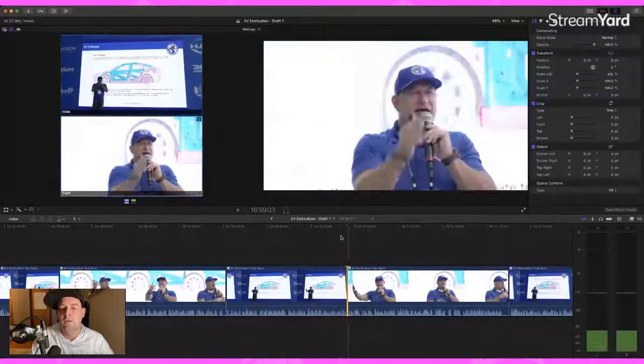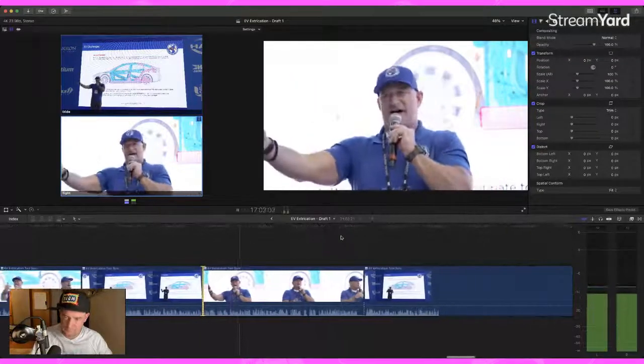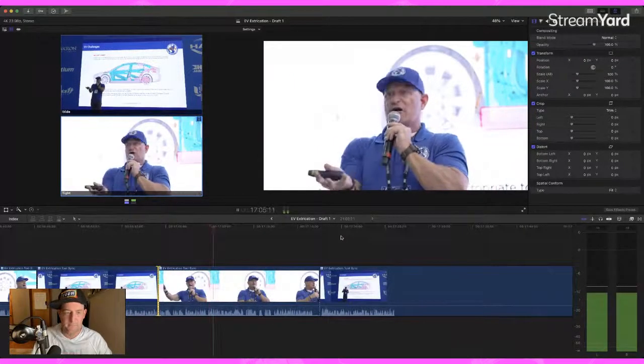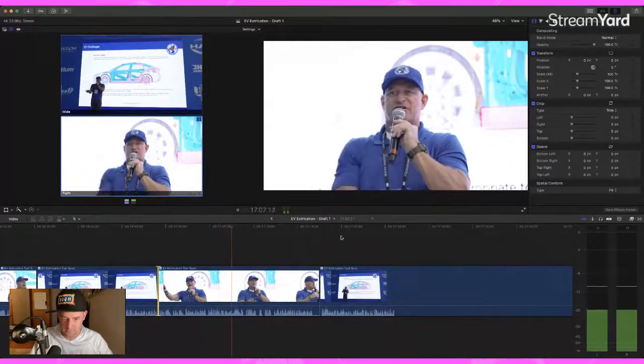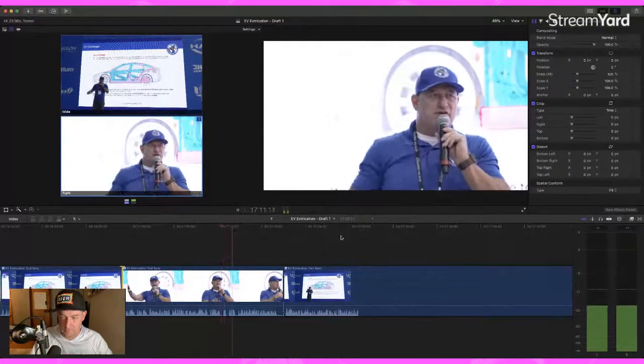Short circuit, it may be hours, it may be days, or it may be weeks after you've done that event, and you will start developing off-gassing at a much slower release rate that then will eventually catch on fire.